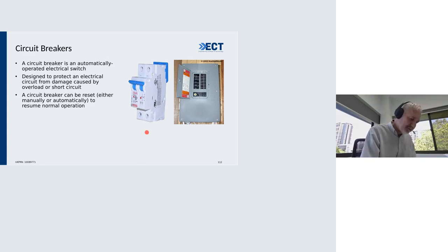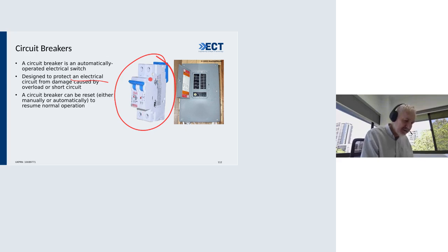Circuit breakers are typically what you see most of the time. You see them in your house, and you can obviously protect your electrical circuit. And when you walk into your house, you'll see a breaker tripped, and then you need to go and identify what it is. So you open all the circuits in the house, disconnect everything, and then you gradually switch each circuit on. And then when the breaker trips, you know, my kettle or my geyser's element is gone, because that's what trips my breaker.